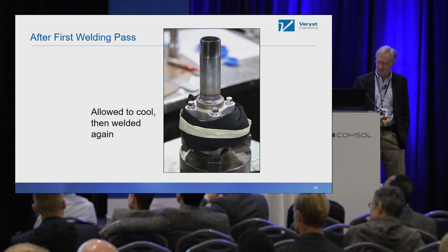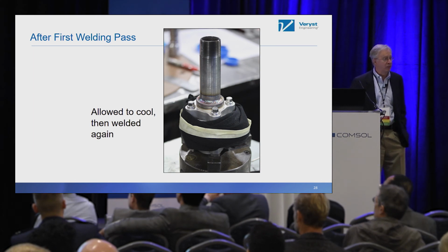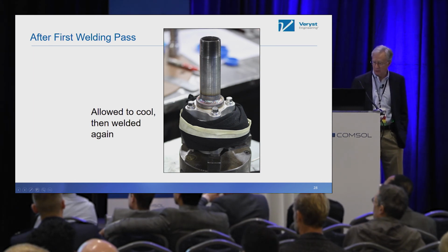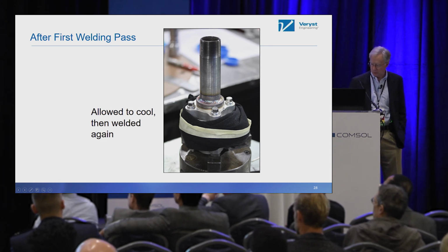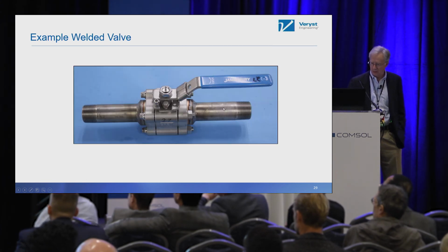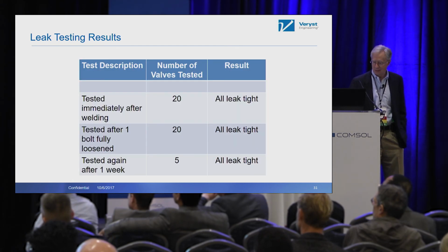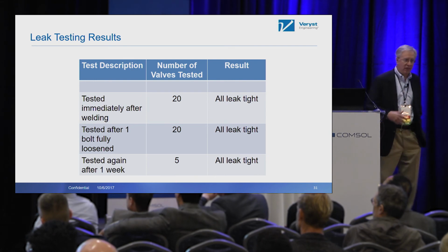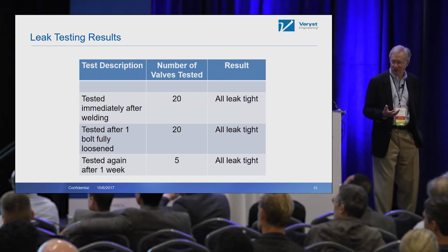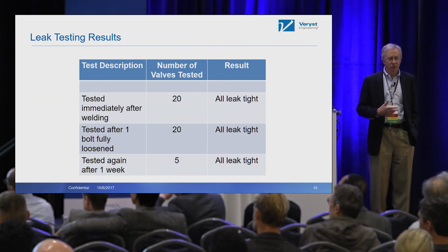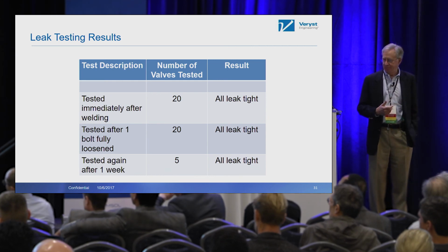We welded them according to the recommended procedure, where we cooled the body of the valve during the welding and kept the weld bead below a certain size, fabricated them, sealed them, and tested them. Under correct welding conditions, we were able to test 20 valves, all being leak tight.